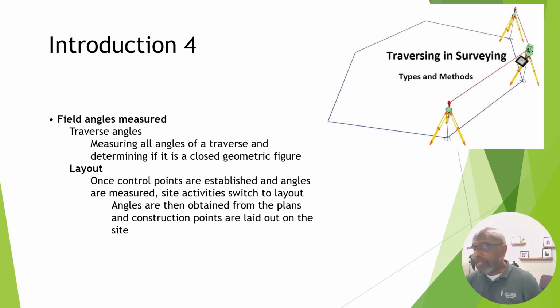When measuring traverse angles, it is common practice to turn the angles at least one direct, and then of course come back reverse, and more likely two direct and two reverse, even for greater precision and to obtain a better estimate of the true value of the angles at the control points.